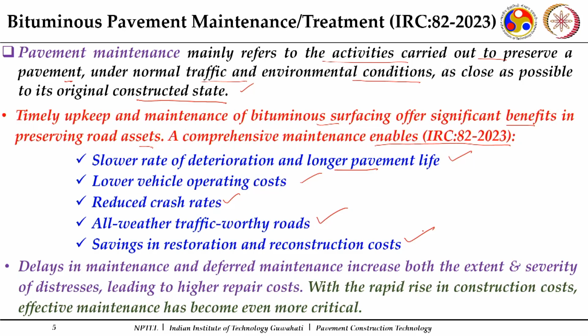Savings in restoration and reconstruction cost: if we are able to upkeep them and delay those, then definitely, because otherwise when major rehabilitation or reconstruction has to be done, the costs incurred are very high compared to these maintenance jobs. Delays in maintenance, or deferred maintenance, increase both the extent and severity of the distresses.